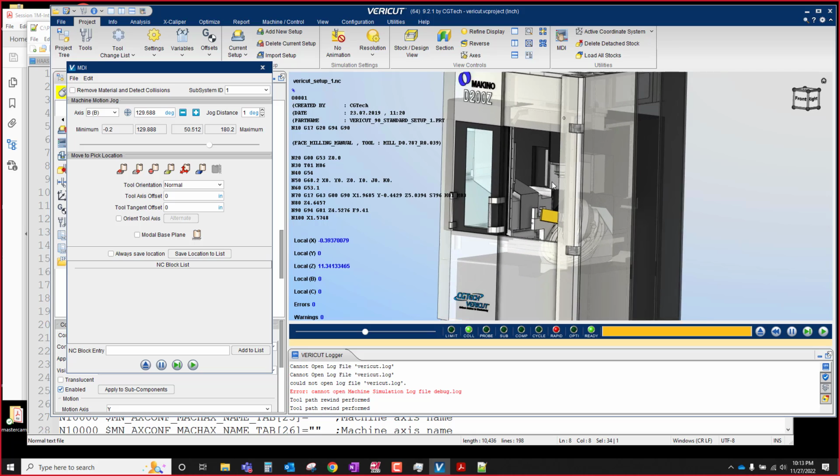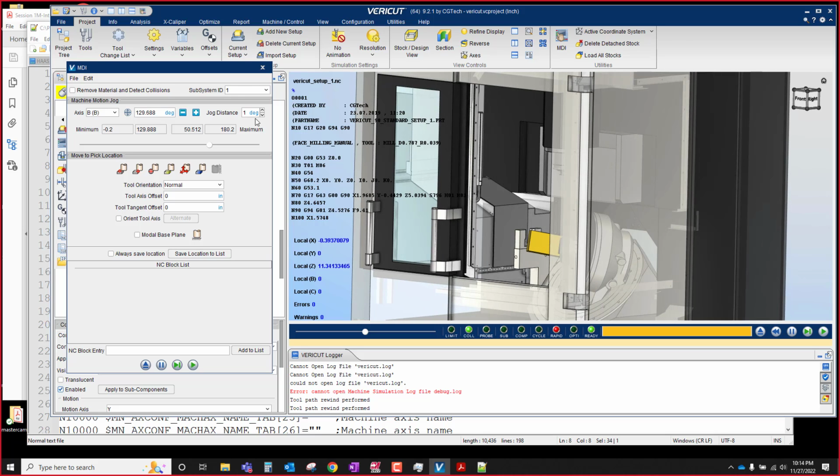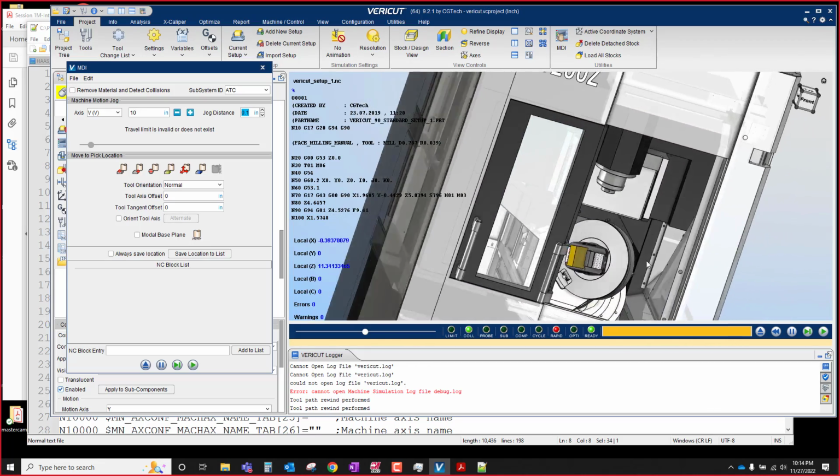In this case, they're saying the tool motion for the tool change is going to go over here, the door's going to slide open, this spindle's going to drop down, and some robot or arm behind the scenes is going to swap out the tool, but it's not in the work envelope, so I don't have to worry about simulating it. But if I go to my ATC, let's go 10. I can open the ATC door. There it is. You know what I mean?